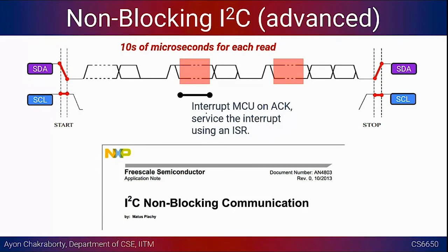Even in SPI or serial communication, all the examples that I've shown you in the driver were using blocking calls, right? So the concept is still the same. If you want a non-blocking version, you use an interrupt, and that's the trick: how are you going to best use the interrupt with the available resources? You can even use a timer.